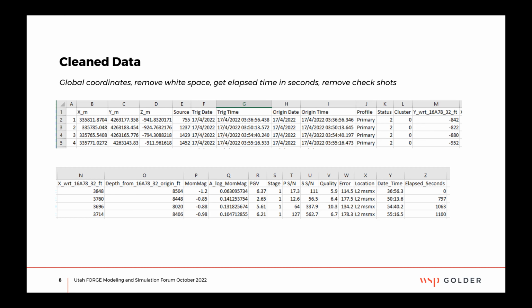I'm guessing Kevin England, who's on the call from the team, could probably answer that question better. So go ahead, Kevin. Yeah, thanks, Rob. Hey, Colin. So the check shot in the open hole was actually a 2-foot perforating gun, and the check shot for the second and third stages was the actual 20-foot perforating guns used to perforate those stages in the casing.